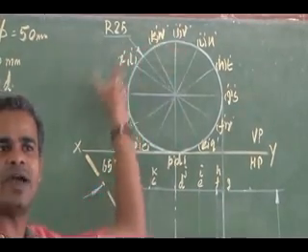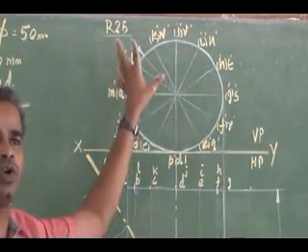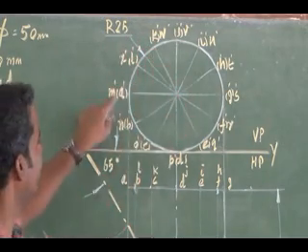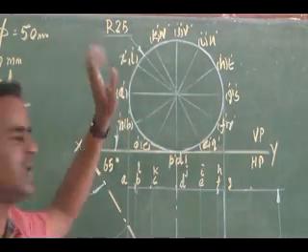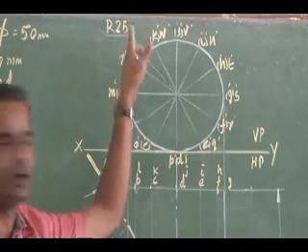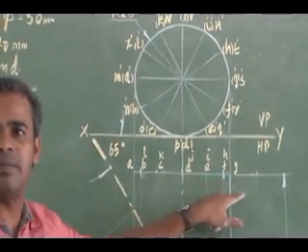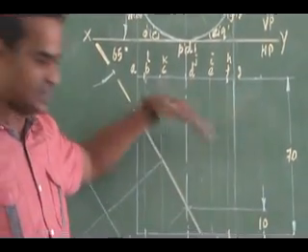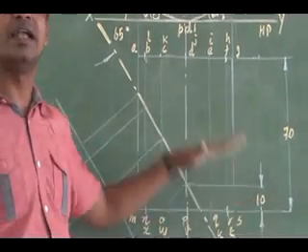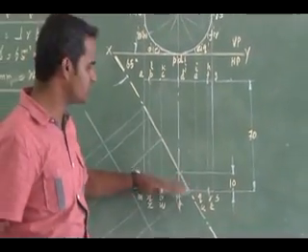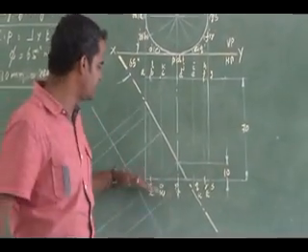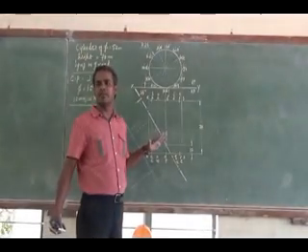So two bases, I have divided into 12 divisions, so totally 24 letters you should have. Starting from A, B, C, D I have marked one base, and starting from M I have marked the other base. The A, B, C, D base in the top view is hidden, so the MN base is visible. The MN base is my nearest base. For you, this is going to be the nearest base in this lying orientation.